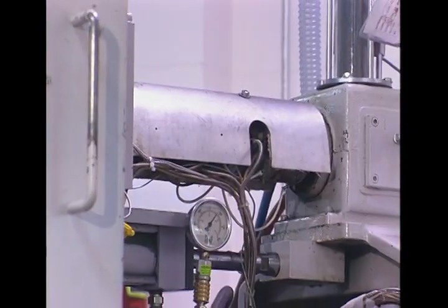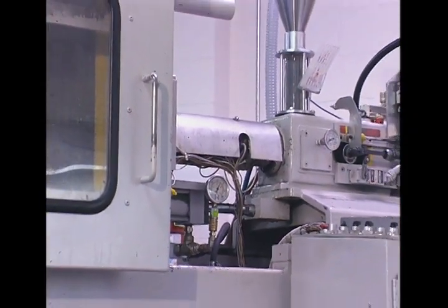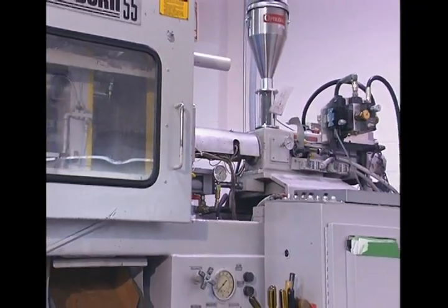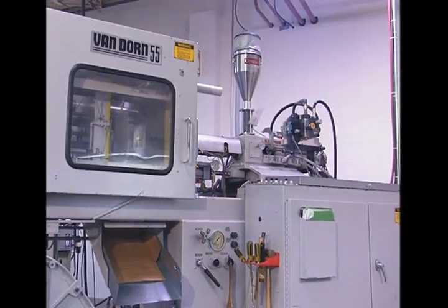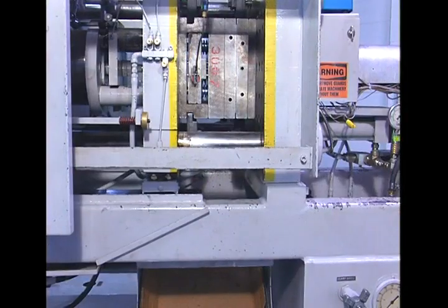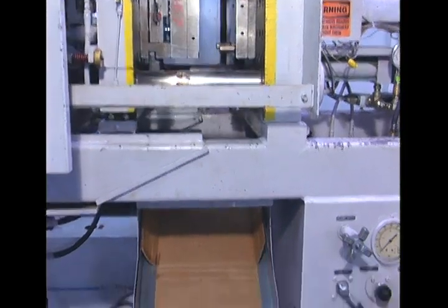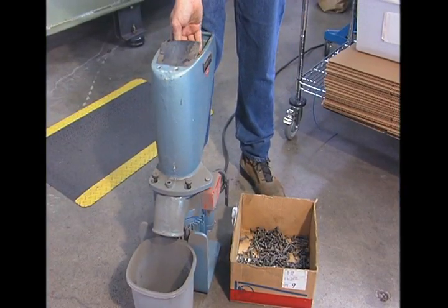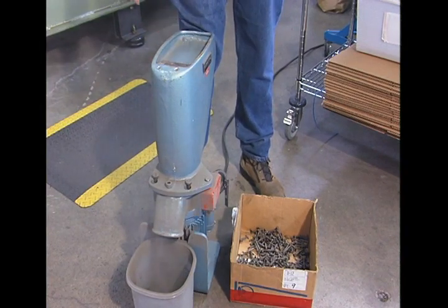The feedstock is heated in the feed barrel of an injection molding machine. Once it reaches temperature, the feedstock is injected into a mold, which may have one or multiple cavities of the part to be produced. Being in the green state as molded, the part is allowed to harden before ejection from the mold. Virtually none of the feedstock is wasted because sprues, runners, and even rejects can be recycled for reuse.